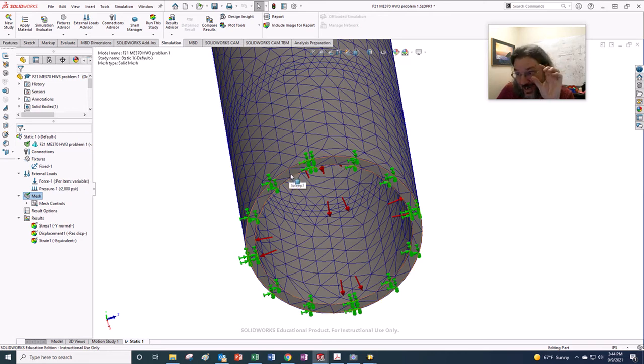We kind of have two, but not really. I wouldn't think of them as having two elements through the thickness. It'd be nice to have multiple elements through the thickness of this, but the modern stress element is formulated to handle things a lot better than old ones used to.